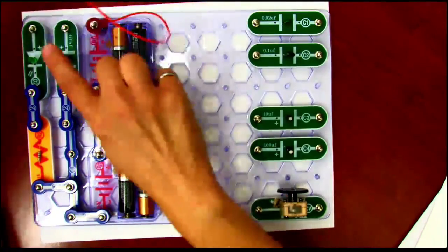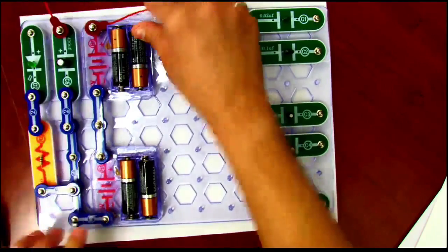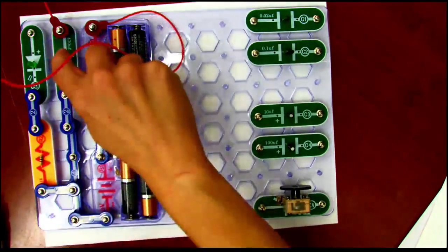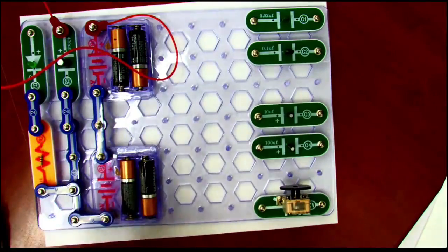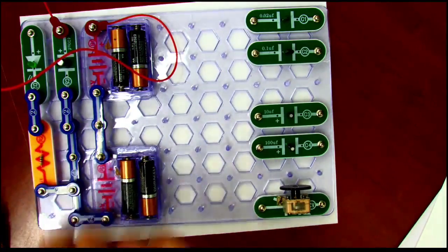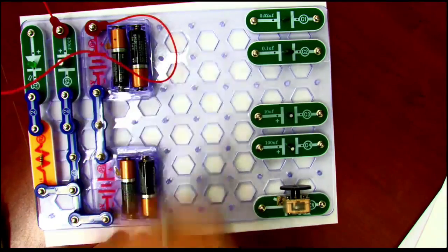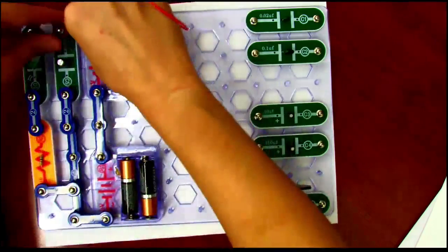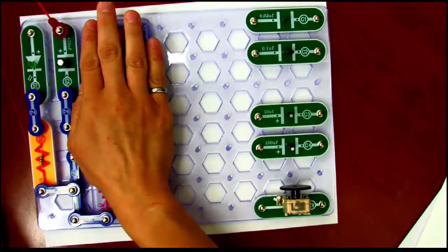If I take my discharge capacitor and connect it to the batteries for a little while, I can build up a charge in it. It has this little spiral of, I think, paper in there, separated by oil. The paper in the oil is the dielectric, and there's some sort of metal coil in there that it's held across, and you're building up capacitance in it. And when it has enough charge, I can disconnect it from the battery, so the battery is completely out of the circuit.